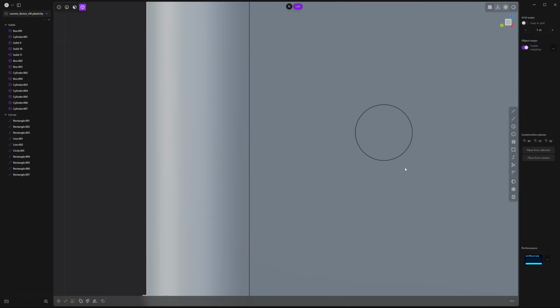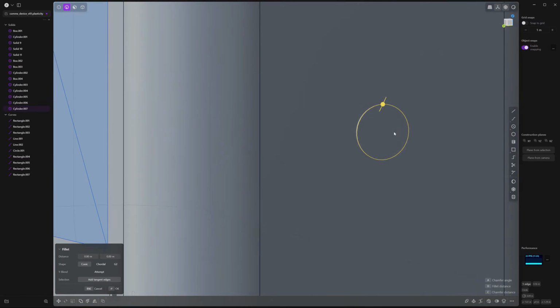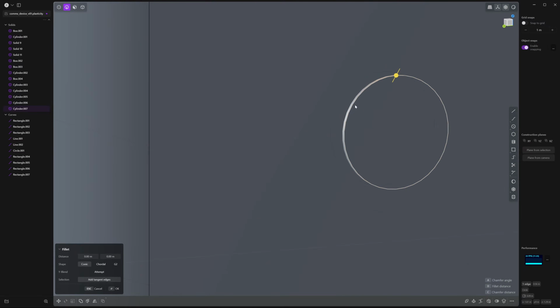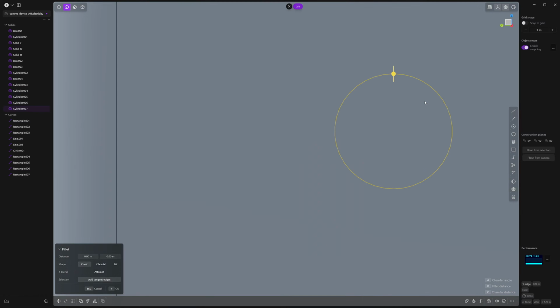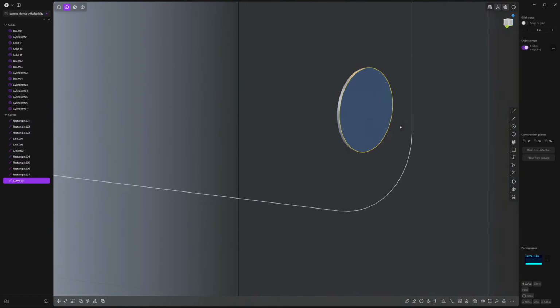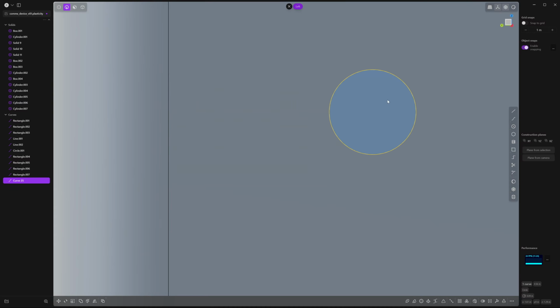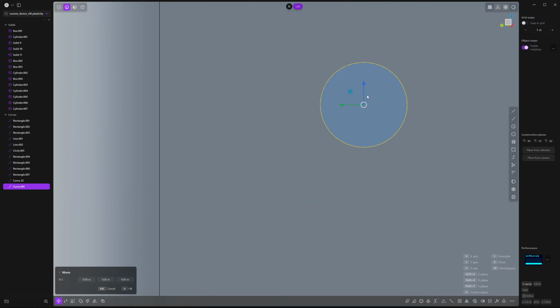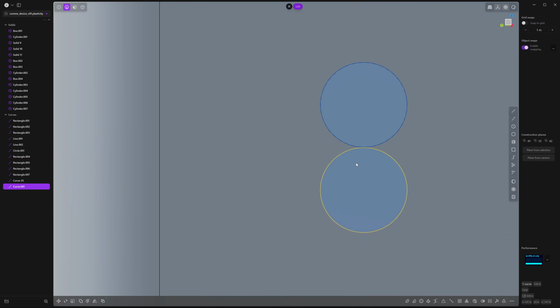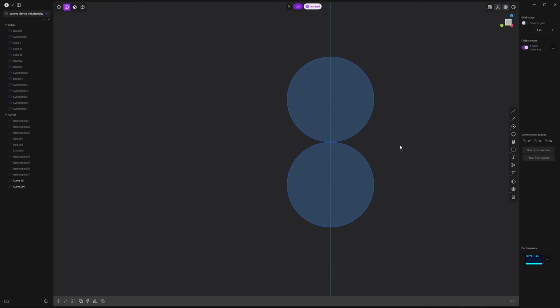And I'm actually just going to duplicate this top edge. So in edge mode, press 2 to go to edge mode, select this edge, and then Shift D. So you see it created a circular curve there. I duplicated that edge. Press Shift D once more, and we're going to move that down. Next, select both curves, press period so you isolate that. Just too many things going on, so I'd like to isolate it.